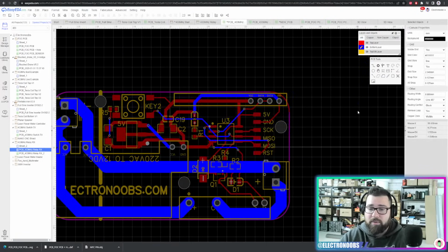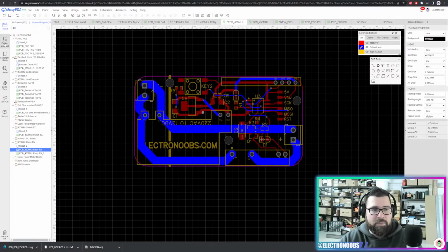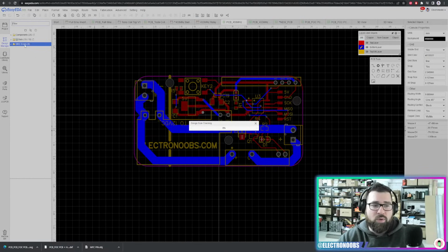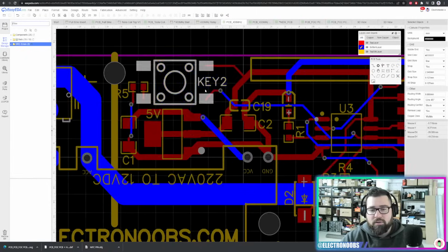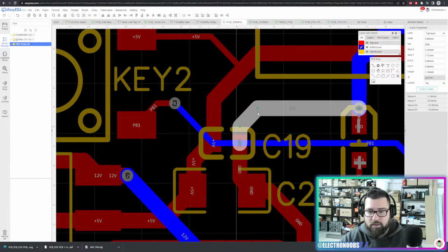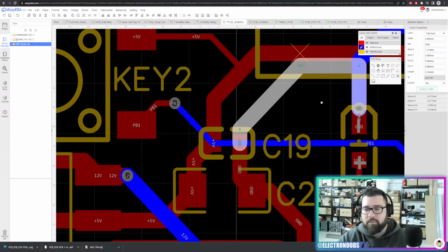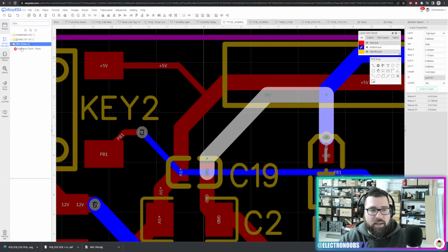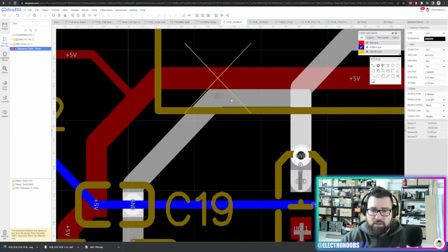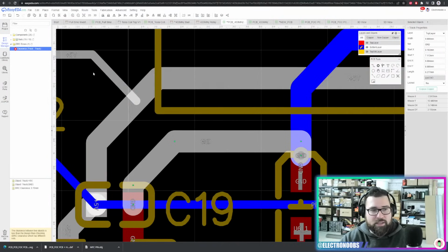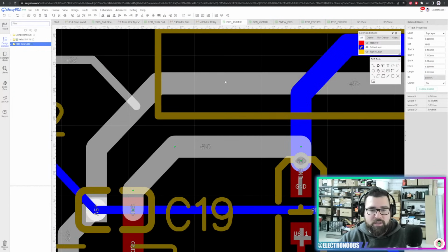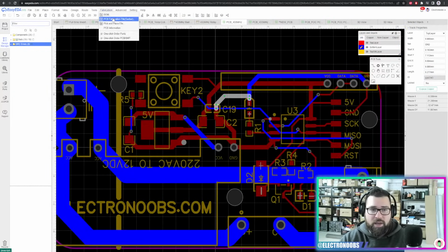And once you have the final PCB, you can just run the design rule check, which is the DRC. And as you can see, we have no errors. And in case that you have an error, let's just, for example, merge this track with the top one. As you can see, we have an error. It will have here a clearance error. You click it and it will take you to that error. You just solve it, save it once again, run the design rule check, and as you can see, if you have no errors,